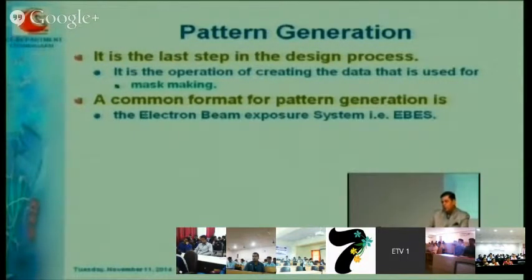Normally we use this system to create different mask layers: p-type mask, n-type mask, polysilicon mask, metal mask, different metal layer masks. Once all these masks are available, we use these masks on the silicon area, we drop the impurities, and then we come up with our chip design.